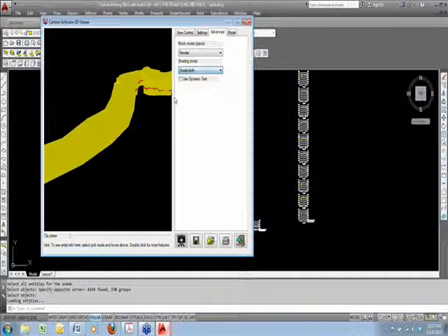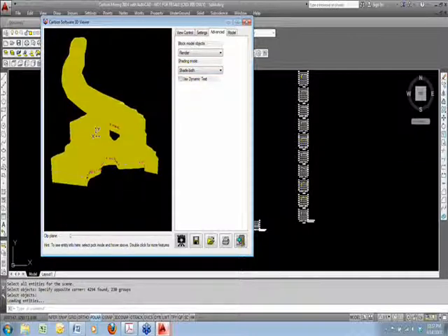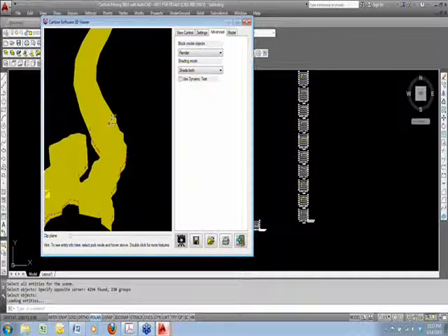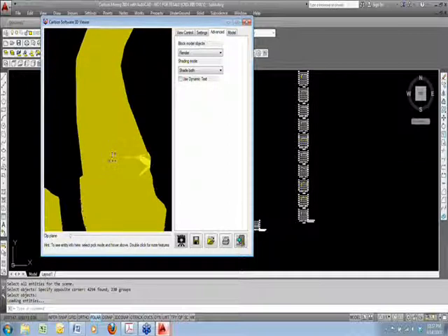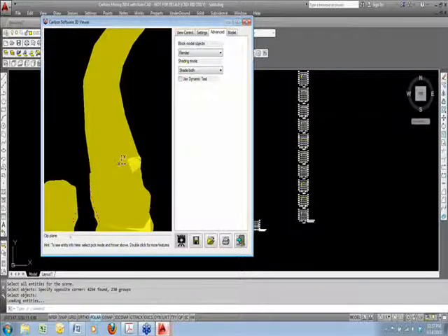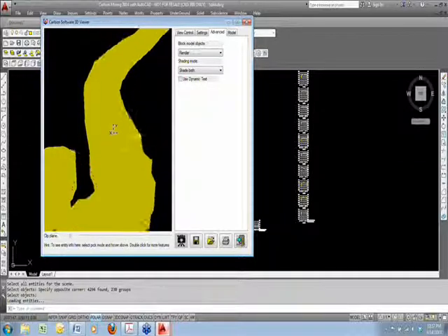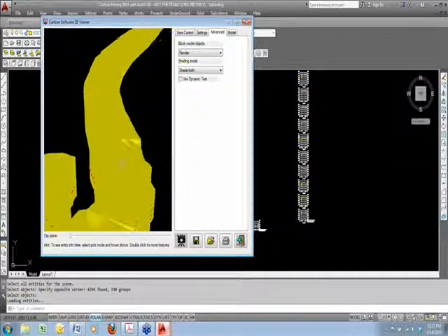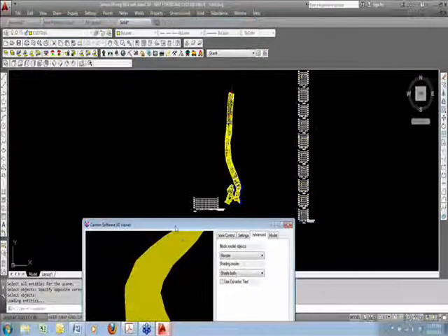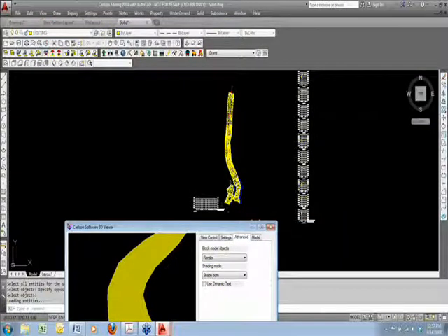So Grant, you have one question. Can you make solids from point cloud data from laser surveys? You can, yes. The point cloud data would have to be arranged into a little bit more layerized, based on what it is. For example, in these points I had here, they had points for the roof, points for the floor, and points for the sides and the ribs.